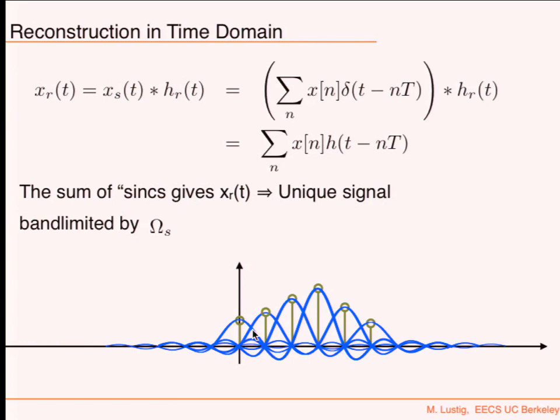various sincs that are basically infinite. And then I just start adding coefficients, and then just playing those sincs, right? One at a time. So you can think of a machine that produces a sinc that's centered at 0, a machine that produces a sinc that's centered at 1, and so on and so forth. And you just put a voltage on them, and then let them play. Okay. So that will be a digital to analog. But of course, it's not great, right? Because it has infinite support. So I'd like to do something that sometimes has finite support.